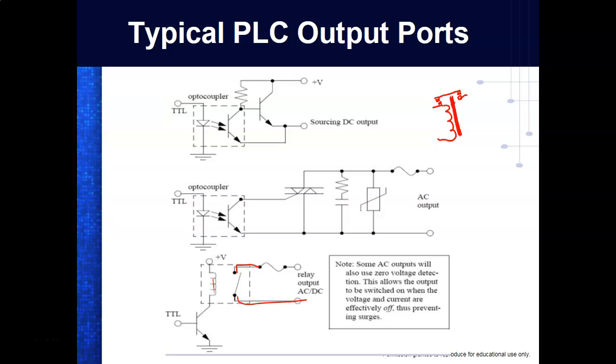So a relay is an electrically controlled switch. So that's what you got in your car. You got a relay box out there in your car. It's black. It's usually over there by the battery. You pop it open, you see all these little black cans or translucent ones. Those are nothing but relays, because that little button you push on your dash to turn on your headlights could not handle the 10, 15 amps required by your headlights. But what we can do is pull in a relay coil using milliamps, and then it closes a switch that controls 10 or 15 amps.